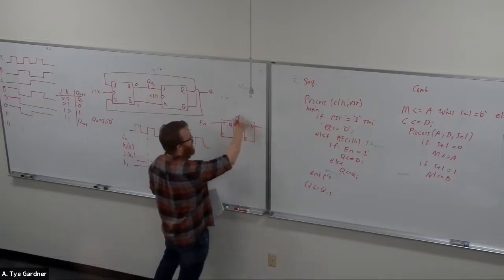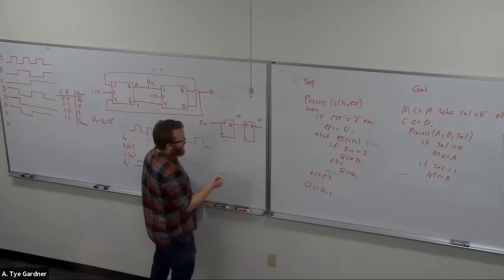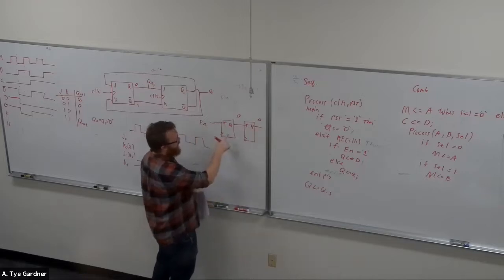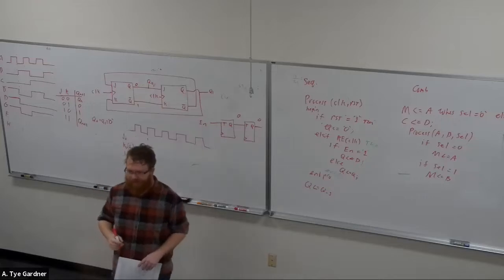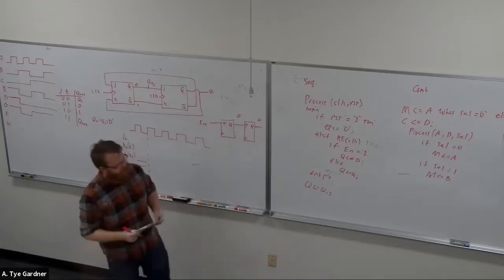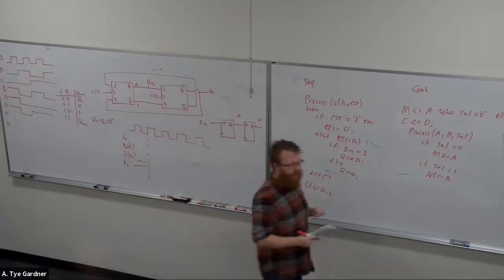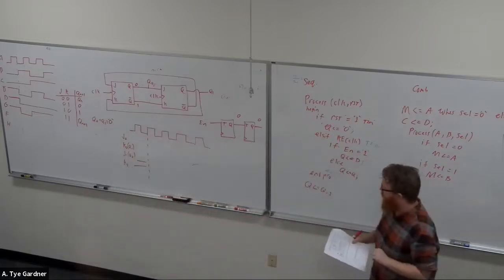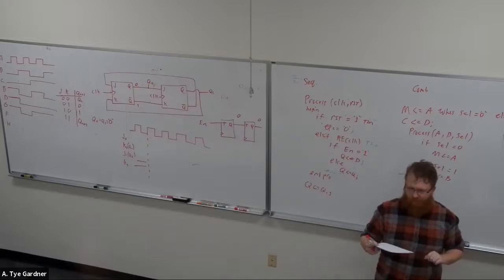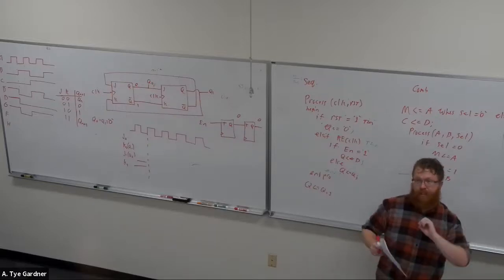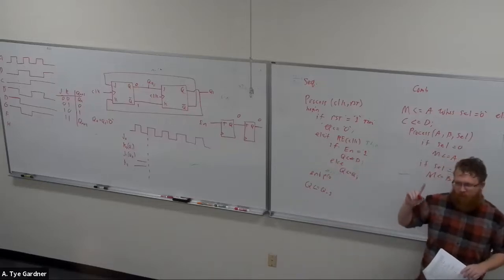Here I would have 0, and let's say I'm starting at 0, 0. Oh, this one doesn't quite work. I need a feed forward path as that AND gate that we talked about in class. This is in your notes: just know how to build a basic counter out of T flip-flops. I could also give you something built from T flip-flops and ask whether it counts. Another good example, different from this one, would be